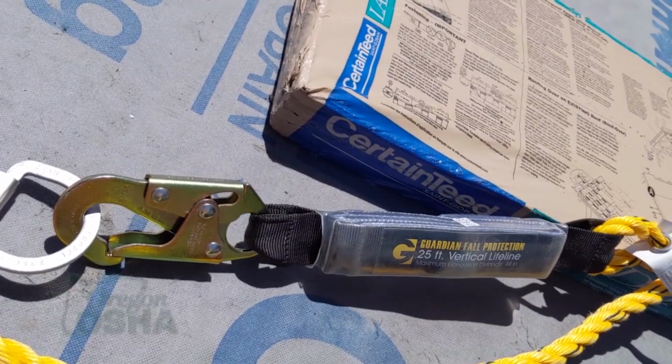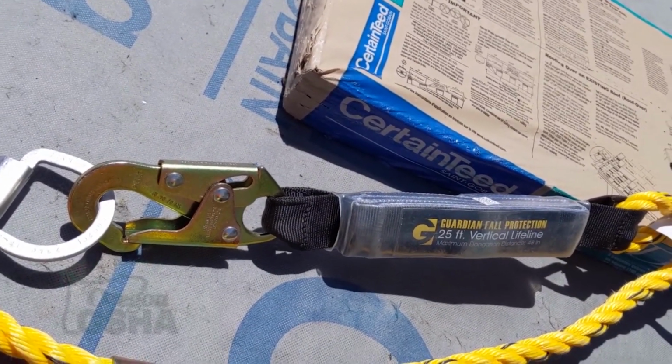So in working on the roof, if someone's working on a 6-12 pitch, for example, we typically will have their rope adjusted to where the rope stops them at the edge. But you do have the lanyard that can still expand if they do fall. And so again, you have to take into relation how tall the person is that's working on the roof, how long the lanyard is, and what your distance from the roof to the ground is.